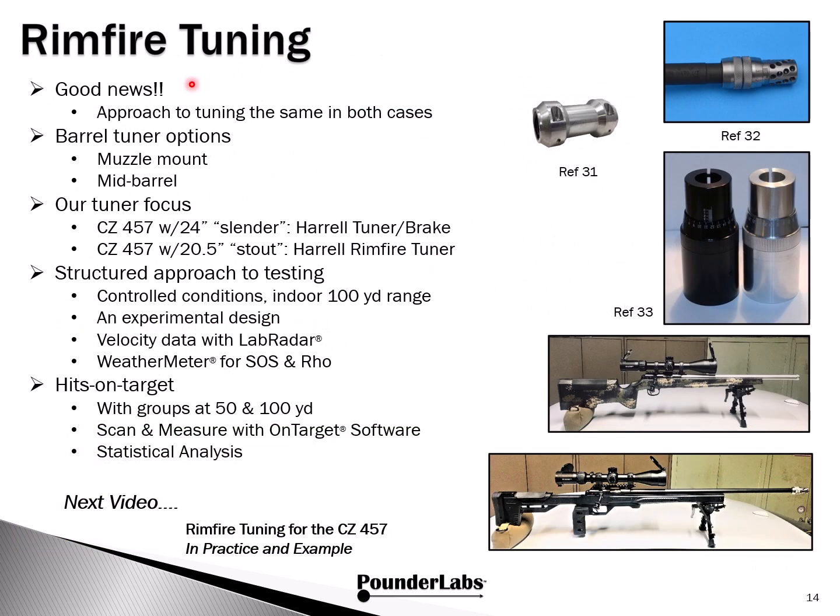If you've been hanging with me through this whole thing, I now have some good news. Regardless of which approach you favor, tuning is done the same way. There's a couple of options for barrel tuners. There's muzzle mount and mid barrel. Here's a mid barrel here. We're going to be focusing on the muzzle mount. It's just simply easier to illustrate our points.